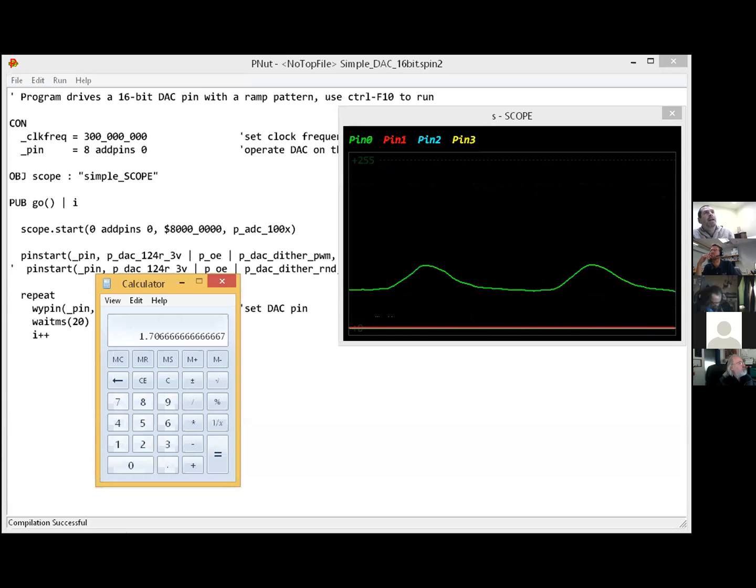You don't have to have any onboard capacitance to smooth it out? Well, the capacitance is kind of virtual, because as these bits come out of the ADC, they're just zeros and ones, and the proportion of ones to zeros indicates the high or lowness of it. If those bits slide through, they're each given some weighted value, and then they're all summed together. That creates the analog value that you see here. So this is a really high-speed ADC mode, but it's not the most accurate. It's just good for looking at super high-speed waveforms.